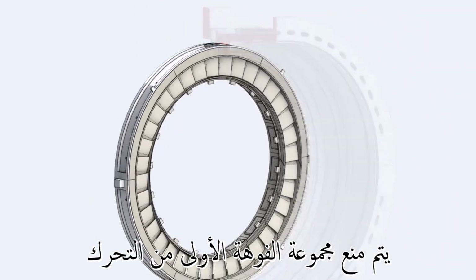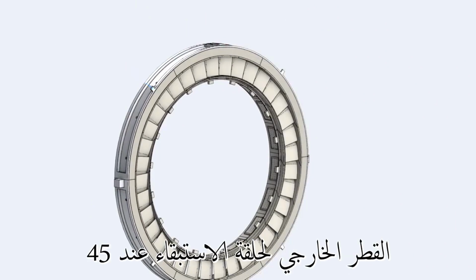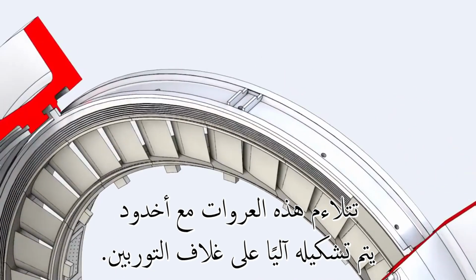The nozzle 1 assembly is prevented from moving forward by 4 lugs extruding from the outside diameter of the retaining ring at 45 degrees from vertical and horizontal center lines. These lugs fit in a groove machined on the turbine shell.